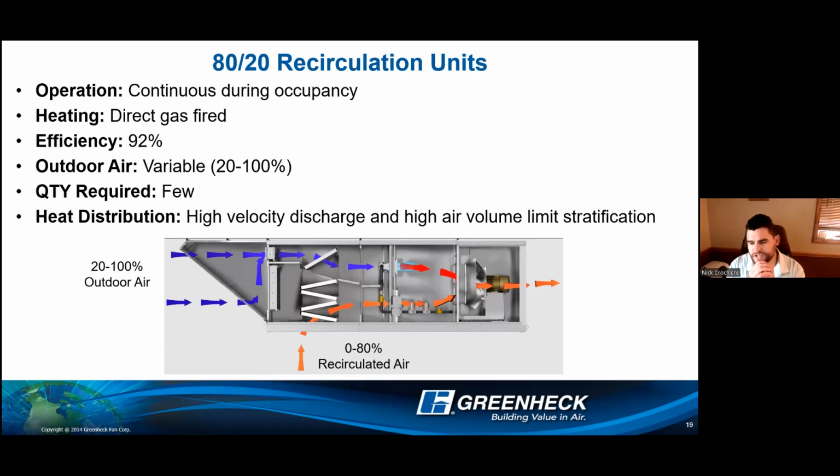So with those units, where do you see them mostly? A lot of warehouses, I would say 75% of the time, are 100% outdoor air units. When are you going to see this? Possibly a smaller application is when you'd see a recirc unit. Why? They would put a building pressure sensor and have their recirc dampers modulate to the building pressure sensor. So say all the dock doors are shut, service doors are shut, maybe it's in unoccupied mode, something like that.